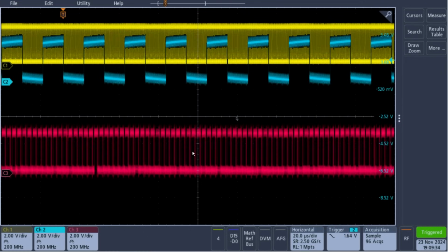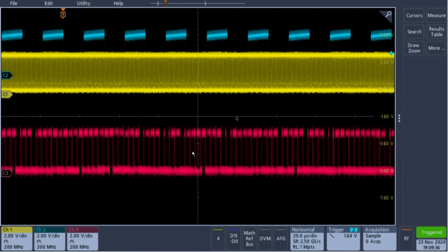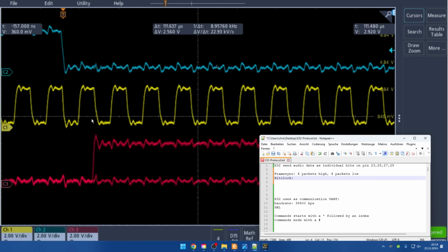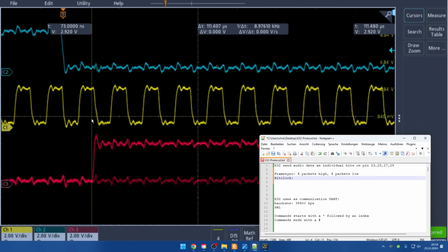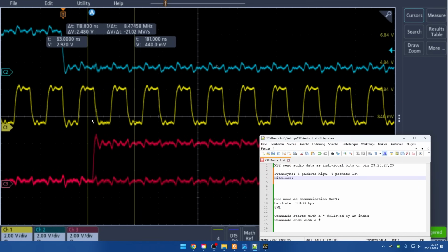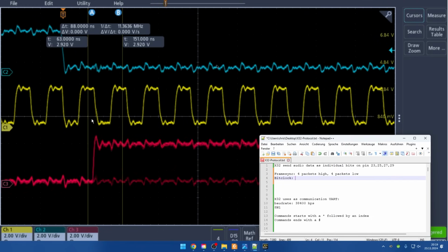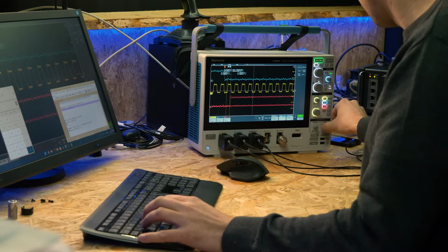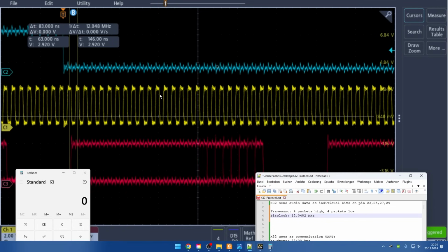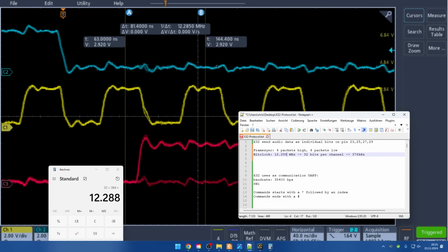We seem to have 3 different clock rates here on the 3 signals. A slow signal, a fast but steady signal, and one with a repeating pattern. Could be audio data. The fast clock signal has a period around 80 nanoseconds, which probably corresponds to a common 12.288 MHz signal. We know that the console works internally with 24 bits, but if we count the individual bits here, we end up with 32 bits.